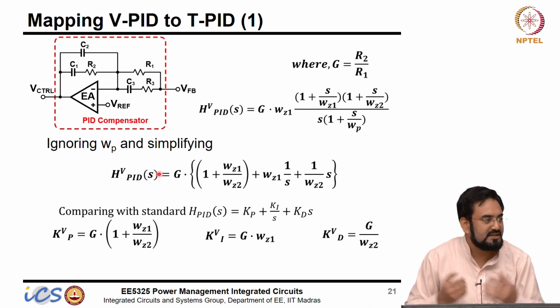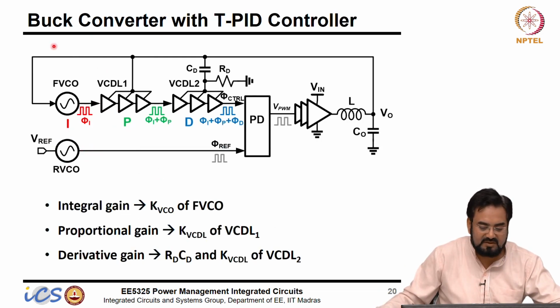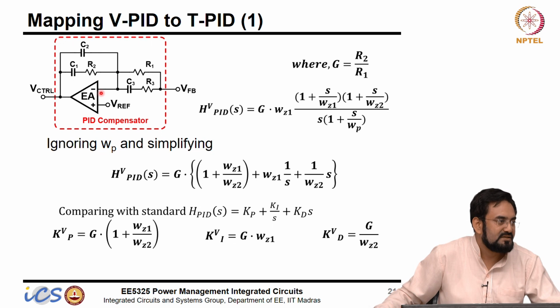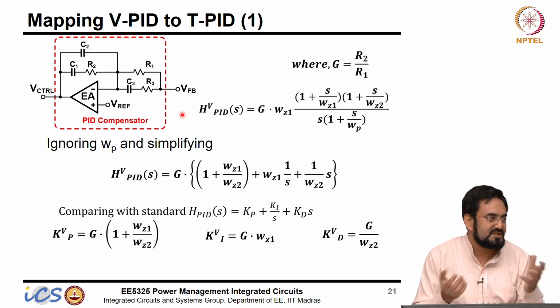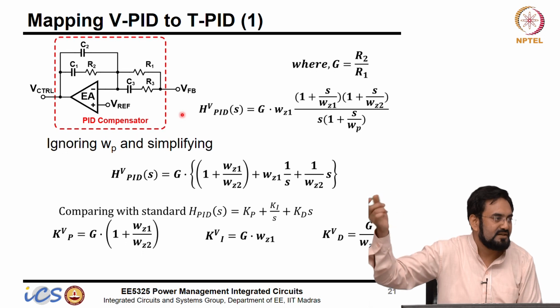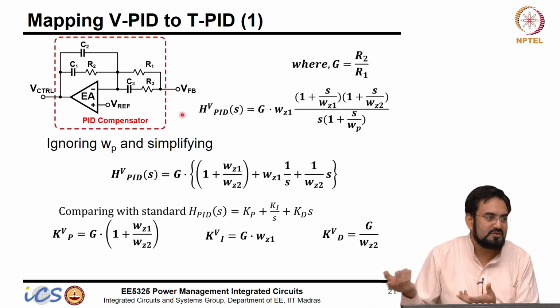We know how to design the voltage mode, where to place the zero and pole, because from here it is very difficult to say where the zero and the pole are, but here we can easily tell. So we always look in terms of poles and zeros, we never look in terms of Ki, Kp and Kd. It becomes very difficult to understand unless you know the zeros.